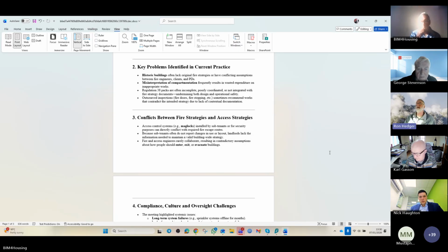For instance, the addition of sprinklers in a business premises is a huge benefit, but it's usually a business or property protection measure. Most fire strategies, if they are recorded at all, will just say sprinklers are provided. They don't say why the sprinklers were provided or whether they were incorporated into the minimum package of fire safety necessary for safe operation. It is very important that the reasons for fire precautions are recorded in the retrospective fire strategy as well.